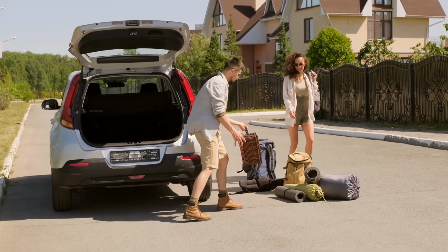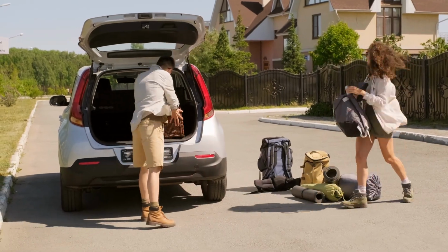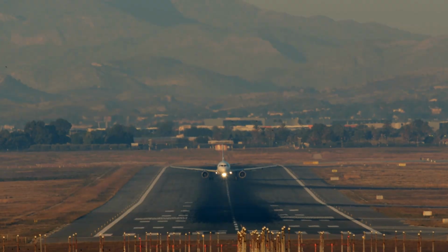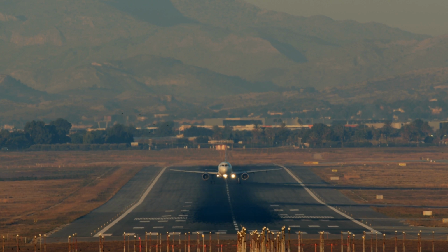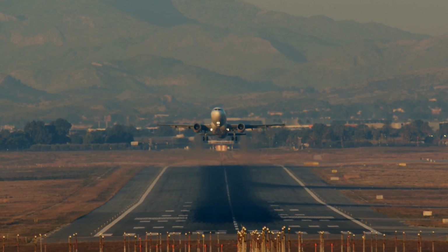Chapter 10 of the Pilot's Handbook of Aeronautical Knowledge covers weight and balance. Your aircraft isn't like your car, where you can cram it with as much stuff as you can and call it good. An overweight aircraft will have difficulty getting off the ground. An unbalanced aircraft can be difficult to control and may even be impossible to recover from unusual attitudes. In general, an aircraft that is too nose-heavy will have difficulty raising its nose, especially during takeoff and landings. An aircraft that is too tail-heavy will be difficult to recover in a stalled condition.